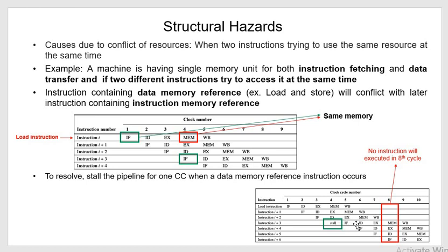So we will assume that only one stall will be introduced, by assuming that only one instruction is a load instruction and the rest are not going to read or write data during the memory access cycle of their own instruction.